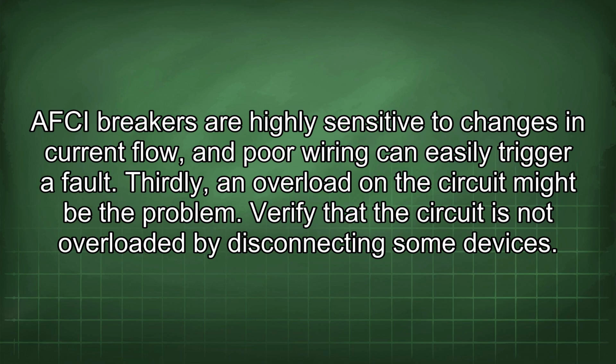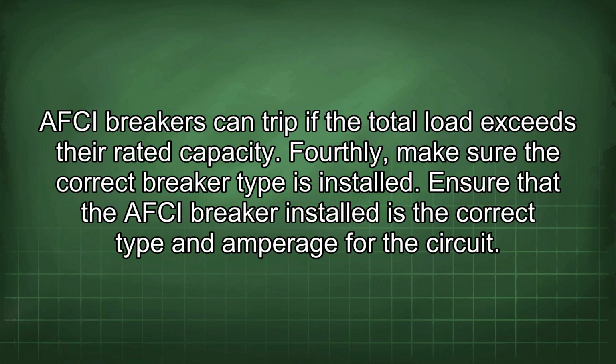Thirdly, an overload on the circuit might be the problem. Verify that the circuit is not overloaded by disconnecting some devices. AFCI breakers can trip if the total load exceeds their rated capacity.